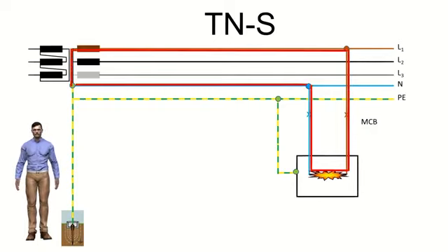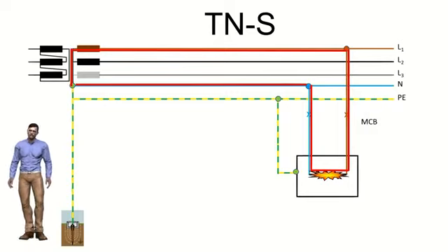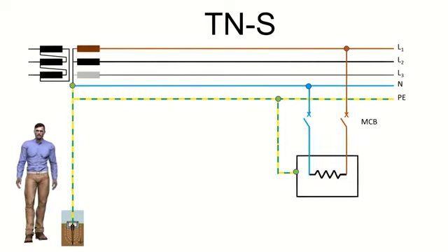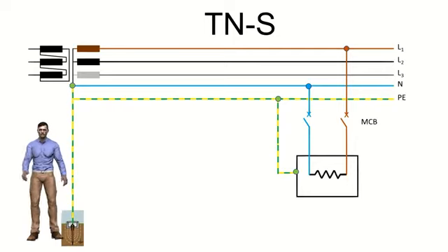In the event of a fault between two phases, the loop that is formed will basically consist of the active cables and the transformer coil, so its impedance will be very small, and in this case a high current will be generated. Remember Ohm's law, which tells us that the current is equal to the voltage divided by the resistance, so the smaller the resistance of the loop, the higher the current that appears. In this case we are talking about short-circuit currents. This very high current must be detected and interrupted by the protection against overcurrents and short circuits, whose function falls on the fuses and circuit breaker protections.